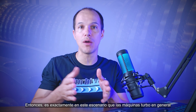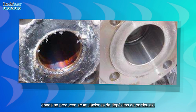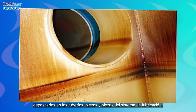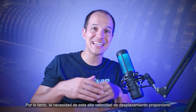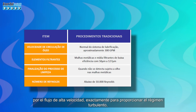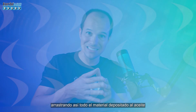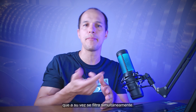So, it is exactly in this scenario that turbo machines in general operate in the low oil flow speed regime, precisely where accumulations of particulate deposits occur. Sludge, varnish, wear and tear, all types of contamination deposited in the pipes, parts and pieces of the lubrication system. Hence the need for this high displacement speed provided by the high-speed flow, precisely to provide the turbulent regime, thus reaching, with greater intensity of agitation, the ends of pipes and lubrication systems, dragging all the deposited material into the oil, which in turn is simultaneously being filtered.